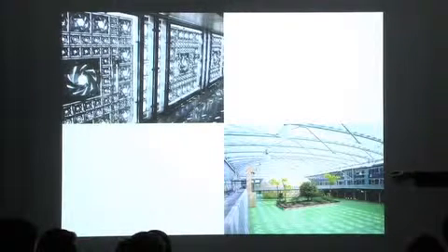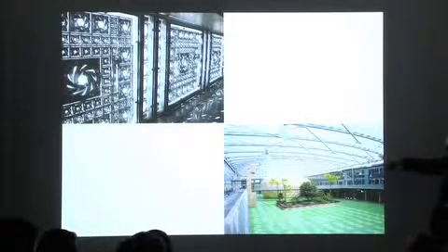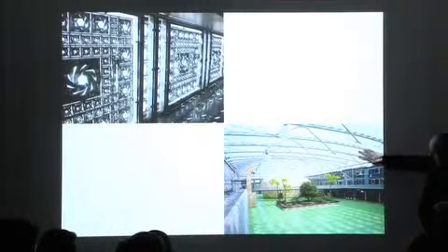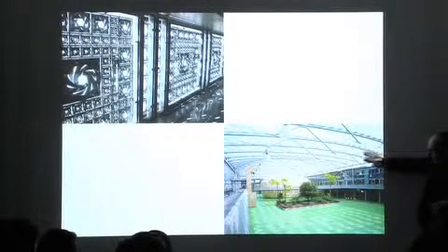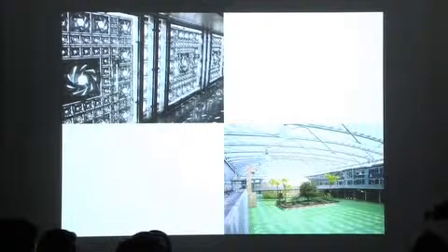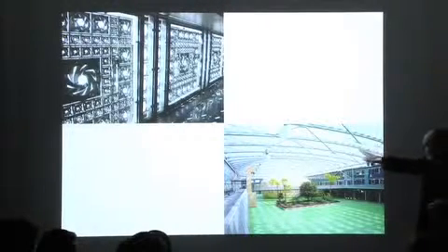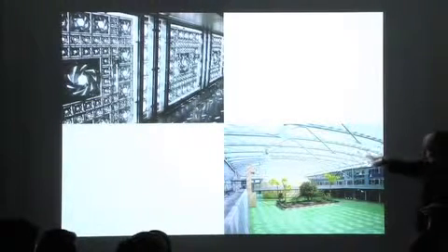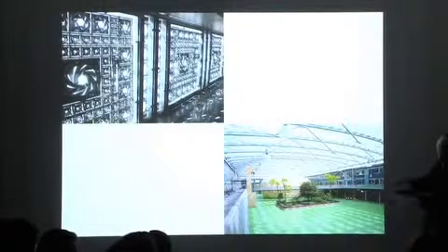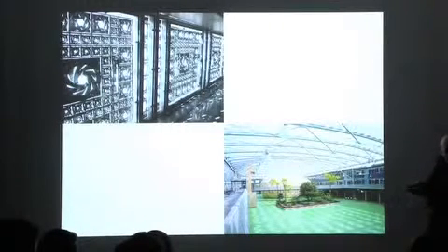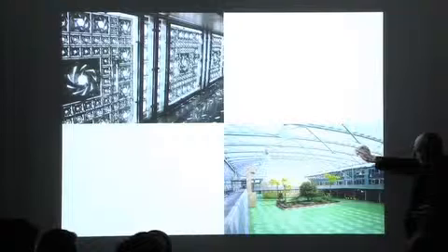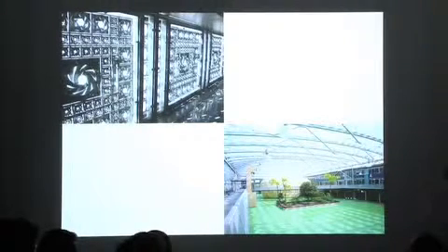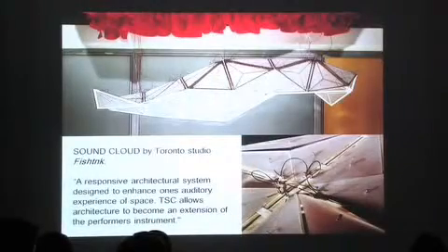This is a school in South London with an ETFE roof consisting of three layers of ETFE, which when it senses too much sunlight, the layers, which have alternate checkerboard patterns, take air out because these are inflated panels. They come closer together, and they darken the space. So they shade the space according to their reading of how much sun is entering the building. So it's quite an intelligent self-shading system.